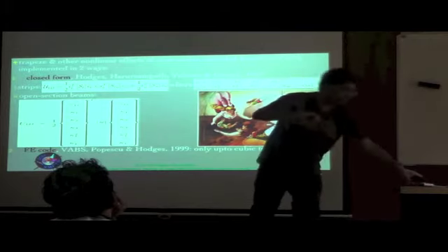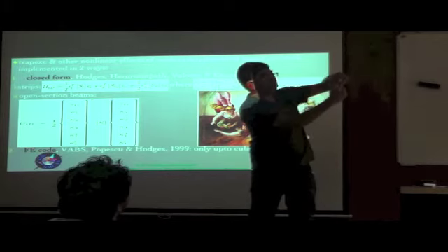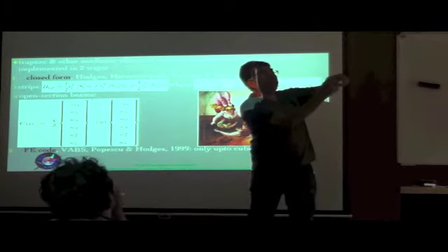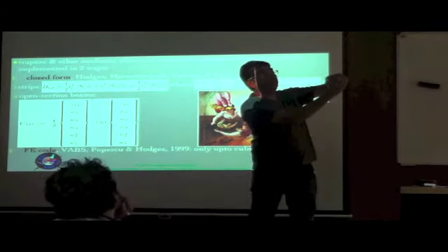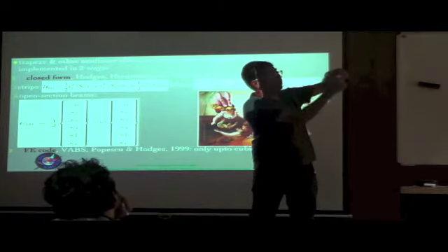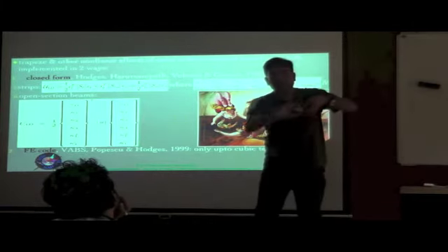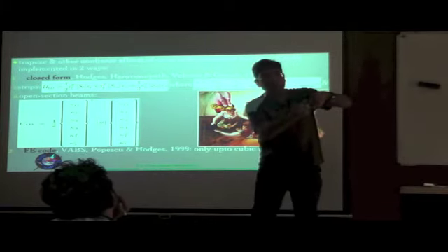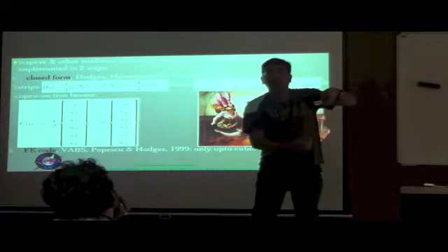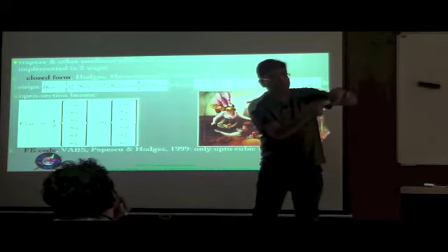Unlike in a circular cross section like this, where the shear flow can go all around, so that the moment arm that you have is basically the radius of the cross section itself. Whereas in a situation like this, when I apply a torque, the way this reacts to the torsion is through a shear flow which comes like this, turns around itself and comes like this.